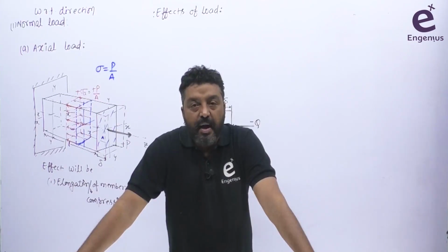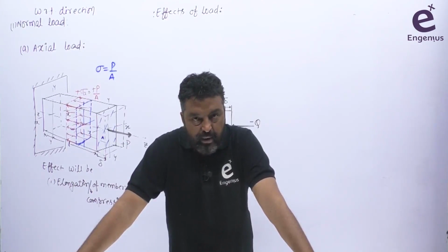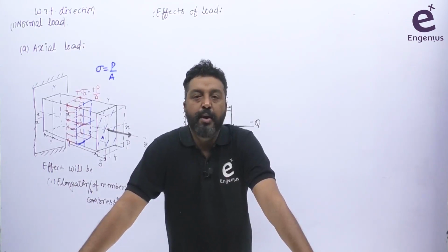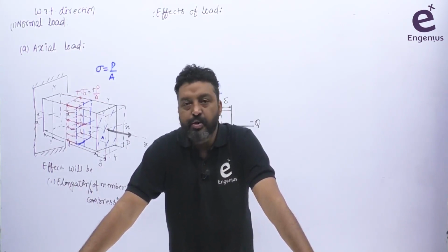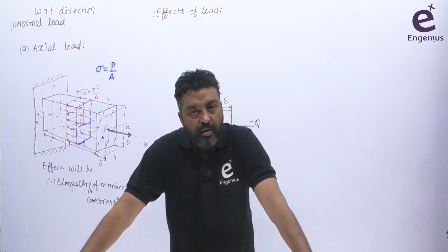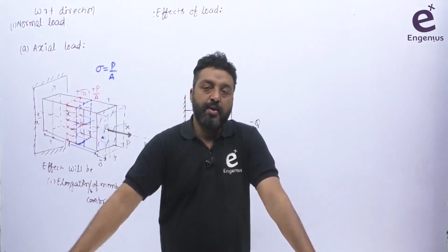There is either elongation or compression of the member due to the loading, depending completely upon the loading, and the axial stresses will be induced in the member and remain constant throughout the length, or throughout every cross section over the member here.